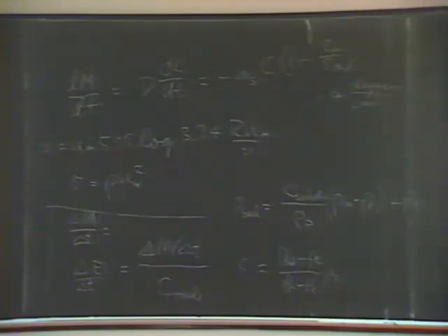So generally, a particular area will have a particular kind of clay, and it's not hard to find out what it is. You go to the library and get the soils reports out on the local lands, and that will tell you. Get some samples and have cation exchange analysis run, and you can estimate the shear strengths and so on from that. But you're right, the sediments vary region by region.